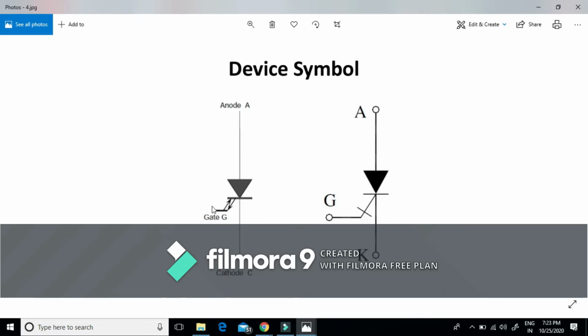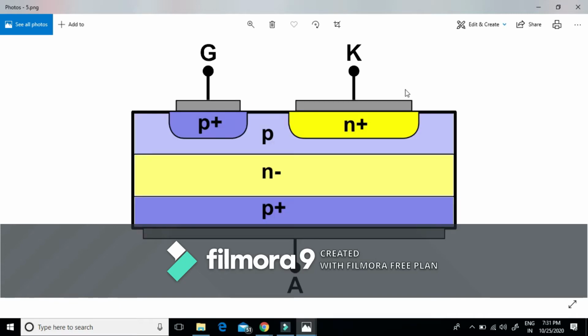However, in case of SCR, the turn-off is not easy, whereas in case of GTO, the turn-off is done by applying a negative gate current of large magnitude. By applying a negative gate current, the charge carriers are evacuated from the anode and gate regions. In GTO, for better reliability, a small positive gate current has to be retained.